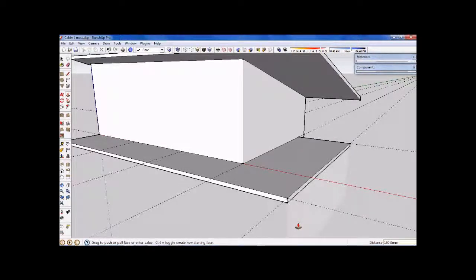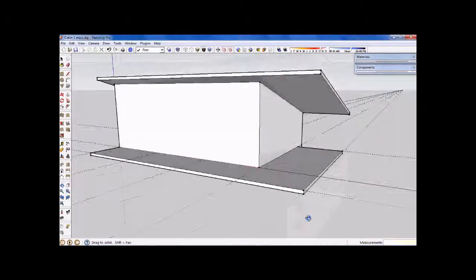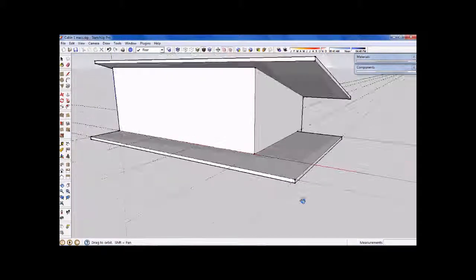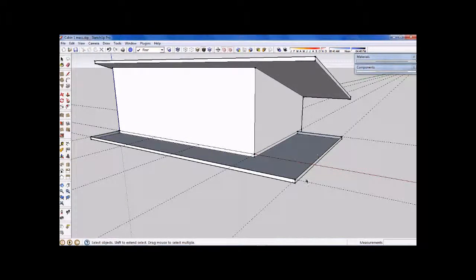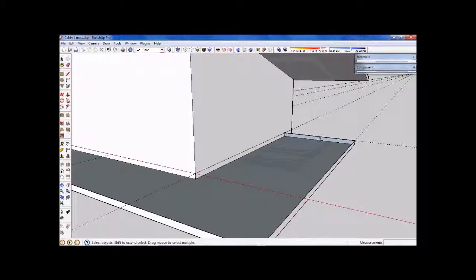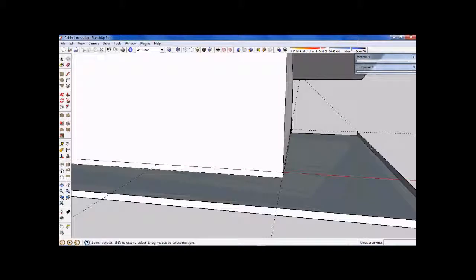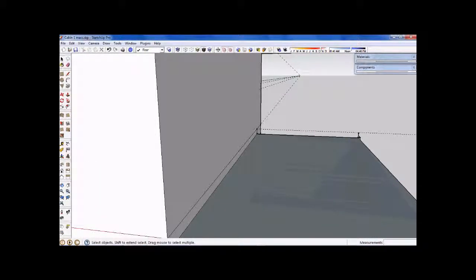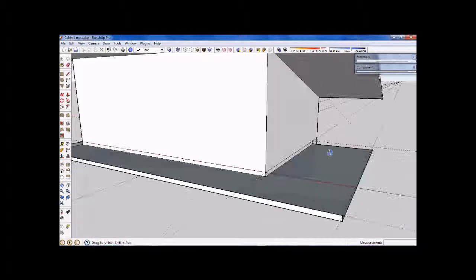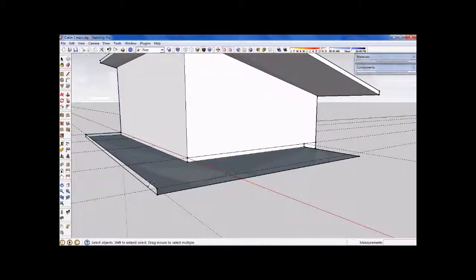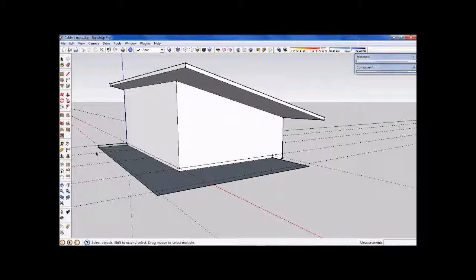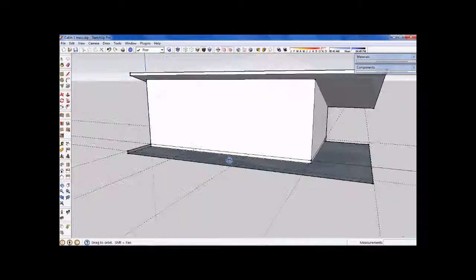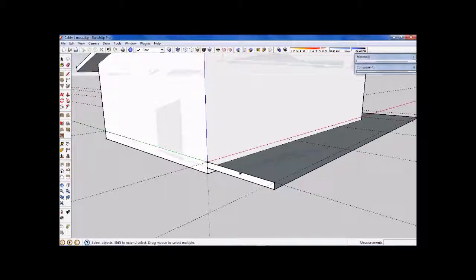And then what I'll do, now that I've pulled it down that 150, is I'll actually select the top surface and delete it. And I'll go around the building selecting these other edges at the top surface and also the vertical edges. What I'm aiming for is the surface that we leave to be 150 millimetres below the floor surface.